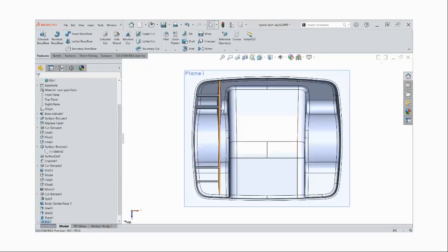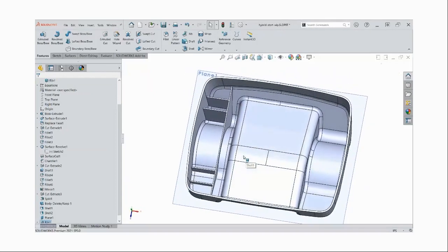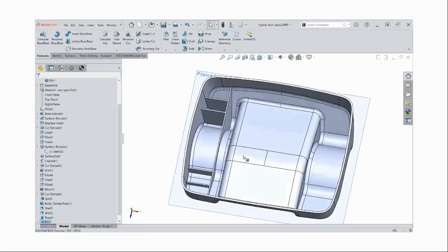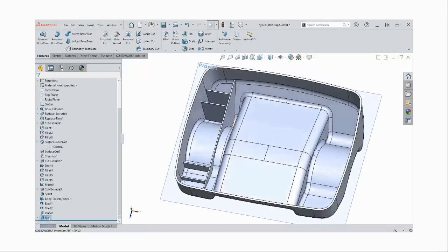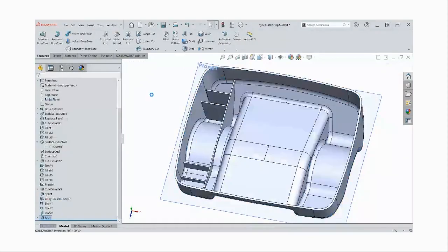But when we look at it from the top, you can see how extremely thick they're getting, because we're only enforcing the wall thickness at the top of them. In fact, this may not be a great rib layout, but the amount of draft you might use on a rib might be more like a 1/2 degree or 1 degree. So I'm going to do a 1/2 degree there, and see that should not be nearly as drastic.